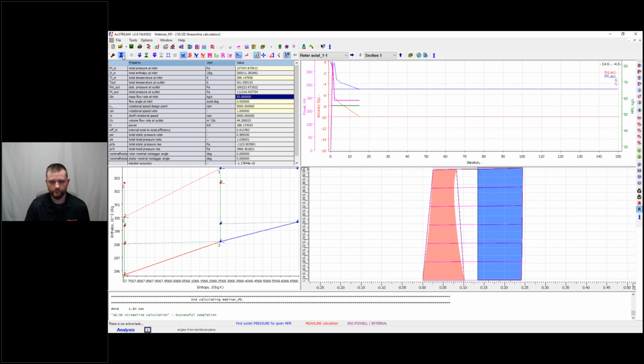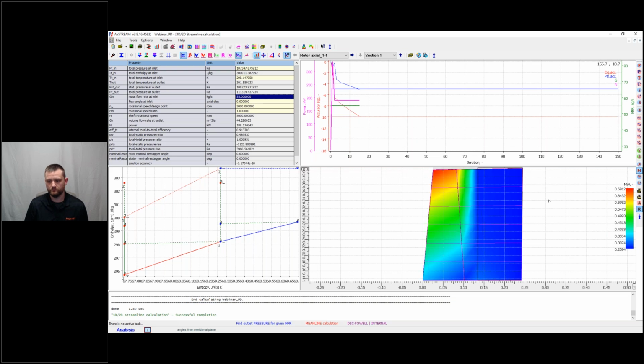Here I can say then if I want to run simply mean-line calculations or streamline calculations to include more sections. You can see these lines here. So it's up to you how accurate you want the results to be. And as I've shown you on the slides, we can have a look at the various contour plots. You see here the Mach number, but also pressure distribution and temperature, which gives you a first insight into how the flow field would look.